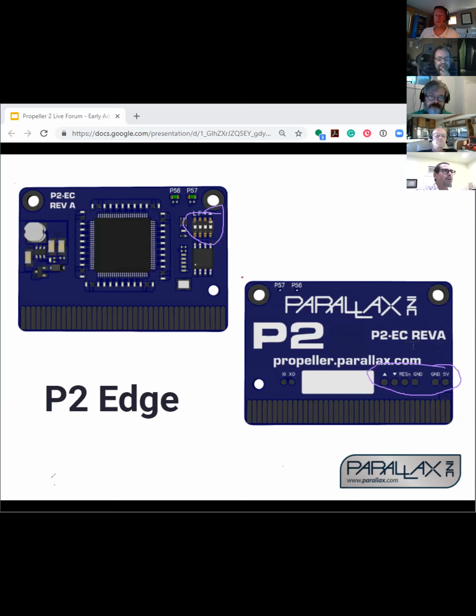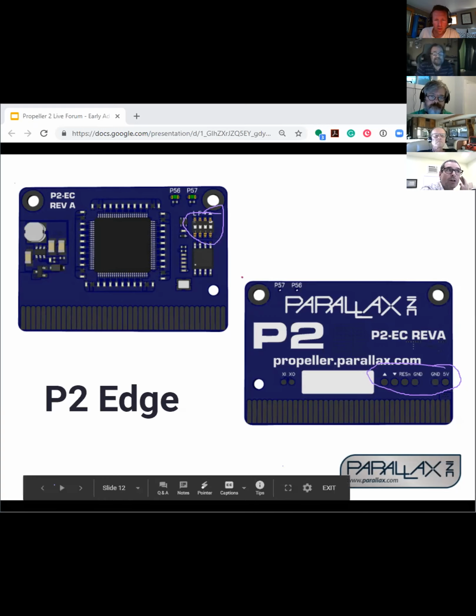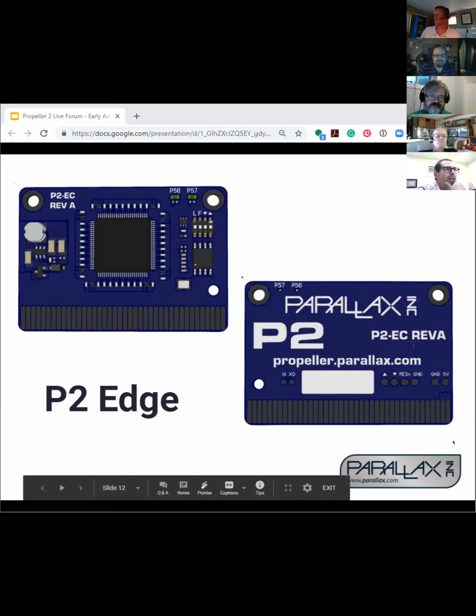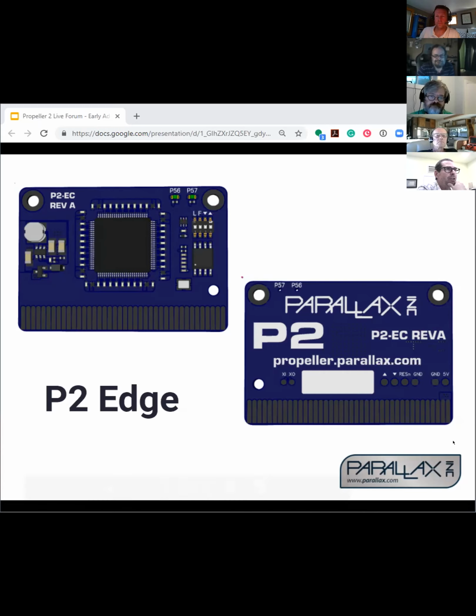Now we have another one underway that is going to have 2 HyperRAMs on it, and we're going to move the flash up above the chip. We might not have to make this thing any taller, and then we'll move the dip switch up there too, and then we'll put 2 HyperRAMs where the dip switch and flash are right now, and they'll be complete. All their signals will be separate, so that we could run both of them concurrently with different activity.